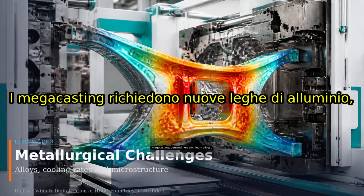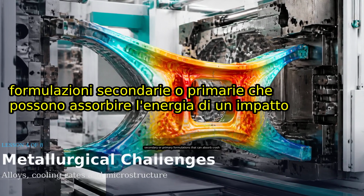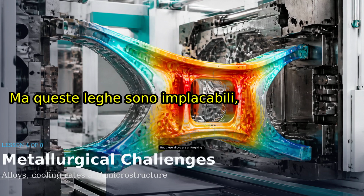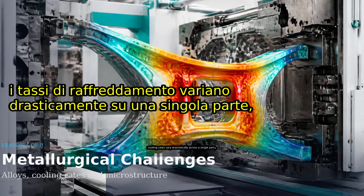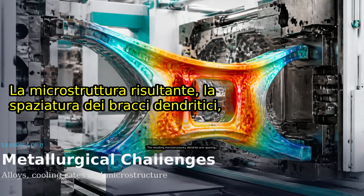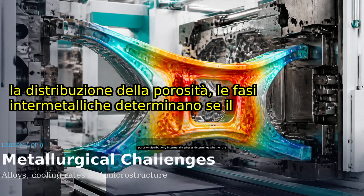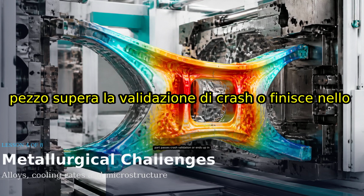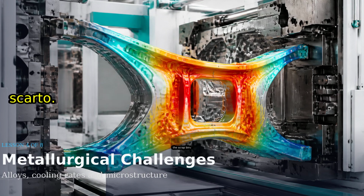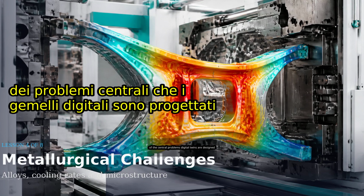Megacastings demand new aluminum alloys, typically high ductility, low iron, secondary or primary formulations that can absorb crash energy without heat treatment. But these alloys are unforgiving. Cooling rates vary dramatically across a single part, fast at thin ribs, slow at thick bosses. The resulting microstructure, dendrite arm spacing, porosity distribution, and intermetallic phases determines whether the part passes crash validation or ends up in the scrap bin. Controlling this thermal history at scale is one of the central problems digital twins are designed to solve.